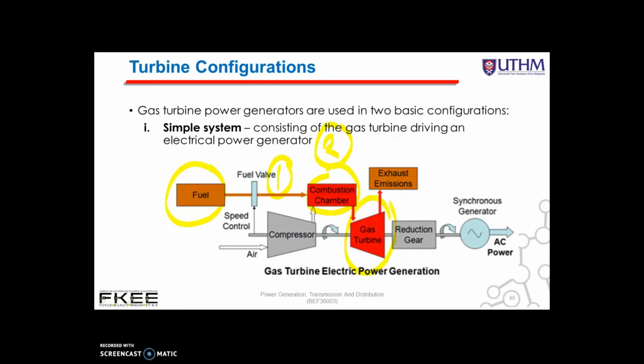Okay, so the third one is the turbine. The turbine is an intricate array of alternate stationary and rotating aerofoil section blades. As hot combustion gas expands through the turbine, it will spin the rotating blades. The rotating blades perform a dual function. They drive the compressor to draw more pressurized air into the combustion section, and they also spin a generator to produce the electricity.